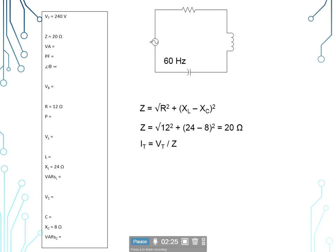Now that we have our impedance, we can find our current total using Ohm's law. So our current total is going to be equal to our voltage total divided by our impedance. Our voltage total of 240 volts divided by that 20 ohms will give us 12 amps.